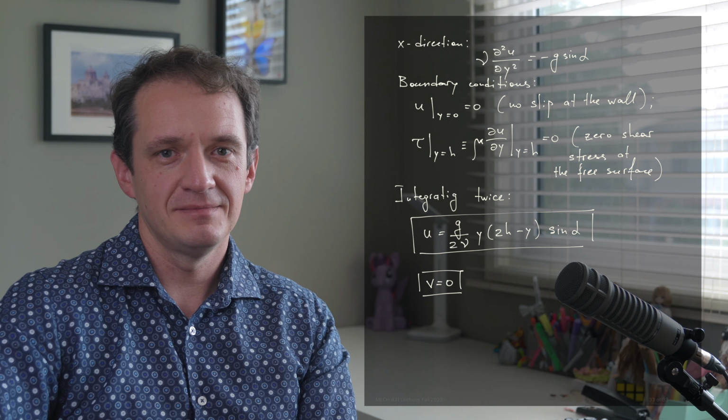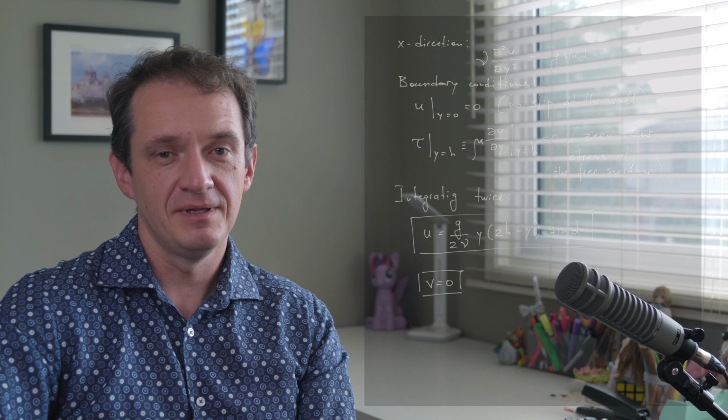So that's going through that example, again illustrating the implementation of some assumptions to simplify the Navier-Stokes equations, and making use of the boundary conditions to evaluate the constants of integration once we find the solution itself.